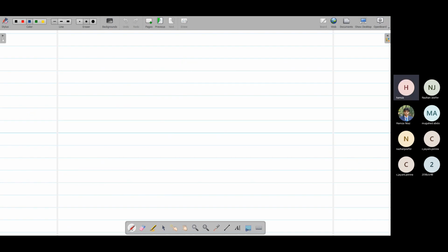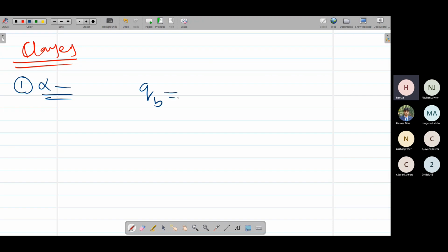piles in sandy strata. The second one is piles in clay strata, the cohesive soil. In clay strata, just like I mentioned before, the only thing different would be Fs and Qb. We have two methods for clay. The first one is the alpha method. For the alpha method, our QB is simply 9 times Cu. Just memorize this. QB is 9 times Cu and Fs is alpha times Cu.